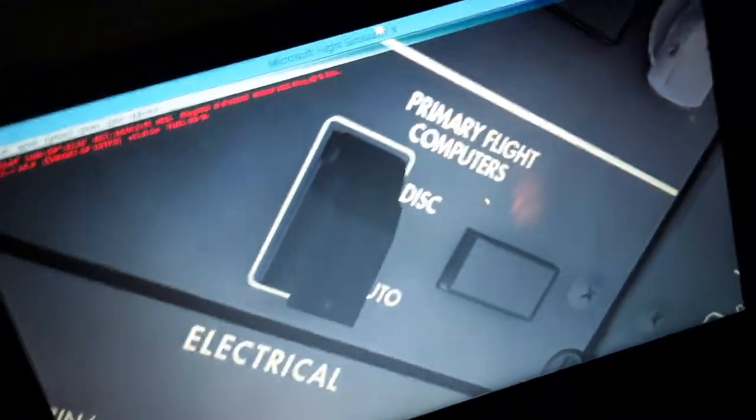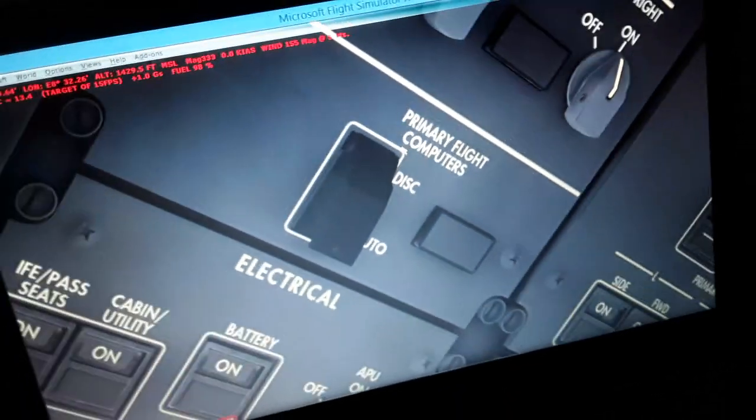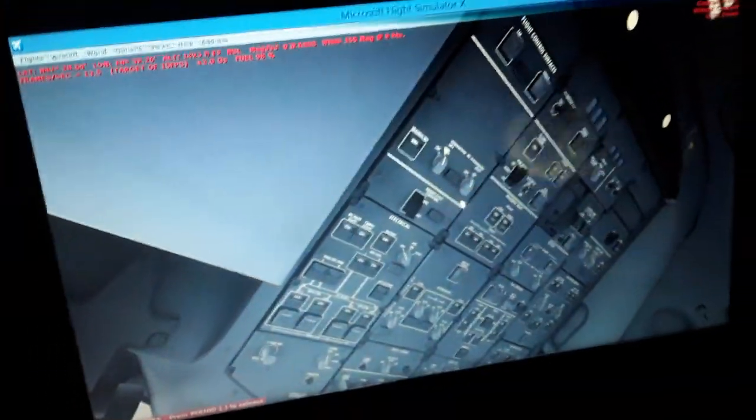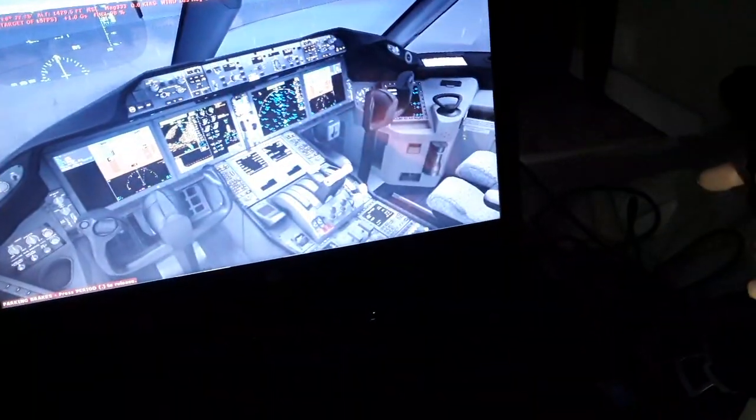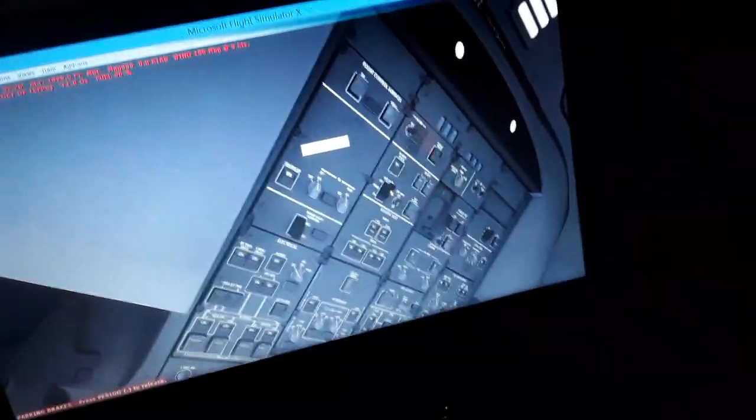Over here you can see the primary flight control computers in the auto position. So this is a fly-by-wire aircraft, like the Airbus aircraft. It has the flight control computers. Fly-by-wire aircraft. It has the normal, the alternate and the direct mode of the flight control channels. So you will see how we're gonna use it for flying this aircraft. We're gonna use also for horizontal trim, stabilizer, autopilot, flight director system panel, and other things we need to do. So the fly-by-wire system, I'll start explaining.